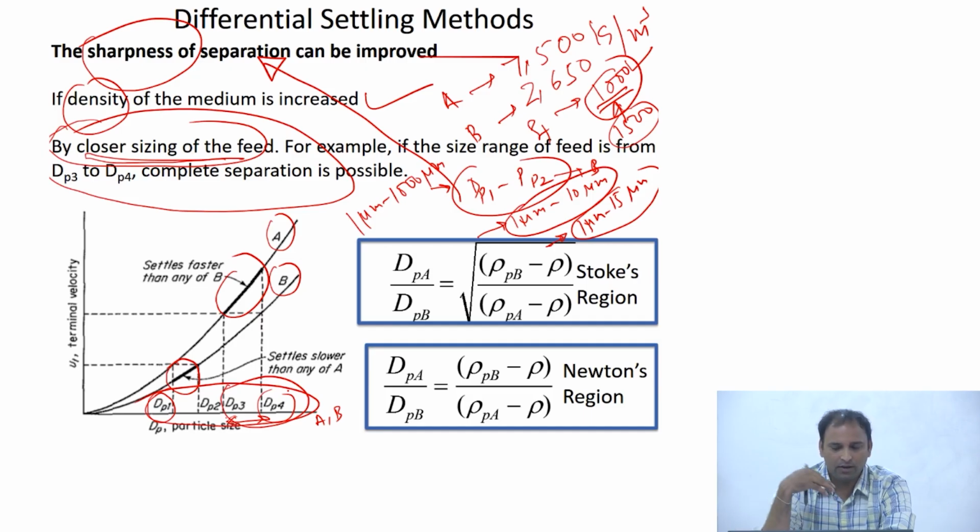We also looked at a couple of examples where people use the motion of a particle in a fluid, the settling principles, to separate out particles if you have a mixture of different sizes and different densities. We talked about the sink and float method and the differential settling method for separation of particles. Maybe with that we'll stop today.